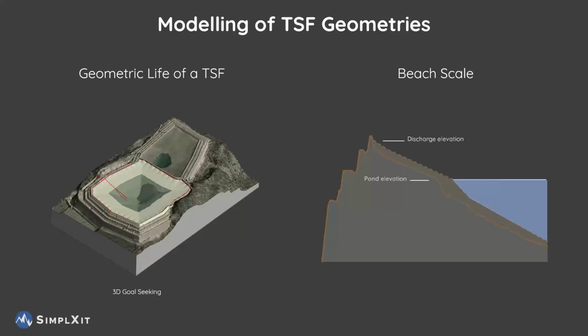On the right side, you saw a 2D goal seeking. In reality, we have a 3D goal seeking. So according to where you have your deposition, it will ultimately lead to different types of new topographies. Once you've done the deposition, the idea is that you also manage the containment of your tailings, so you actually build the containment with it. Ultimately, that's what Muk3D will be doing. It will be about building the containment and running the various depositions.